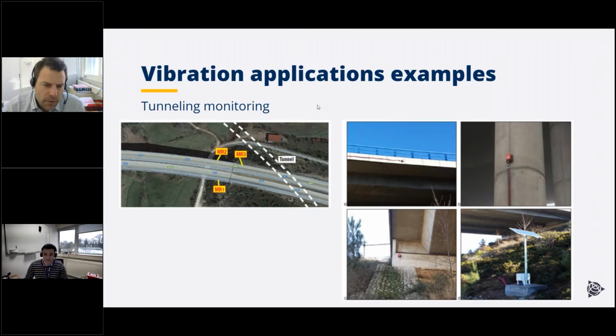Yes, there are a few examples here to give you some monitoring ideas, I would say. I'll go through that quite quickly. Here, this was a project in Portugal, I think, with 3 devices. They were building a tunnel for water irrigation. So they had to monitor the tunnel and the bridge. And you see here 3 devices on the pillar, on the table of the bridge, and on the, let's say, basement of the bridge, linked to a solar panel and some backup batteries. So that was an example of monitoring.